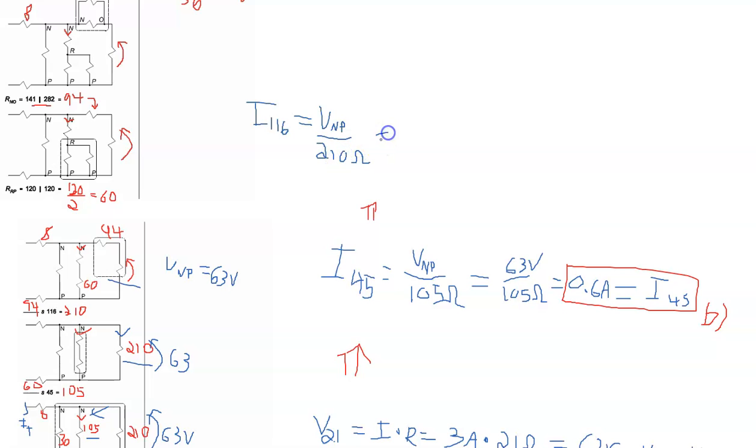And so the current in that branch, we have 63 volts over 210 ohms. And so, similar calculation to this one down here, the resistance is twice as big. It means the current's going to be half as much, right? 0.3 amps. And so that means that, in this circuit here, if I calculate 0.3 in that branch, then up here, I got 0.3 in that branch. Right here, of course, we can bring that information up to all of our parts of circuits.